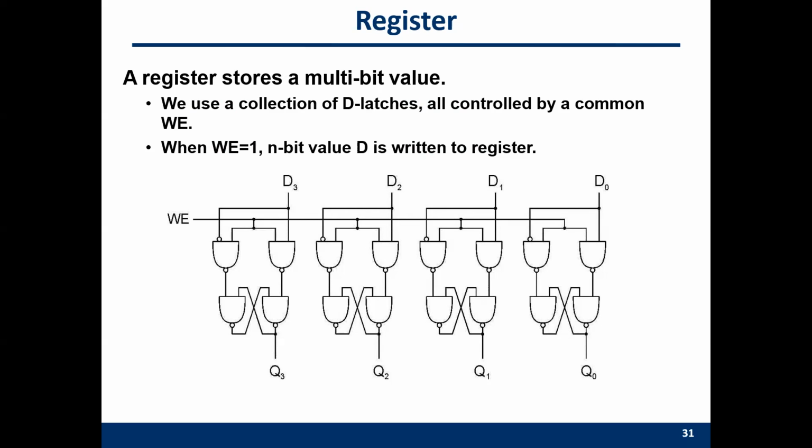And then we can also connect all the WE inputs of the gated D latches to 1 line. So this line is the write enable of the register. Only when WE is 1, you can change the value.